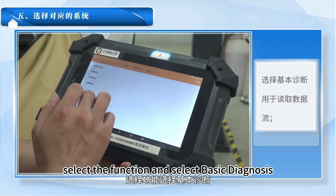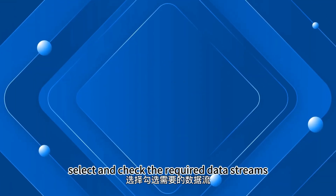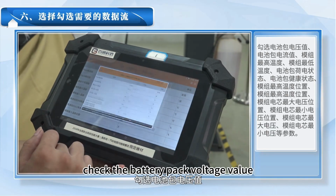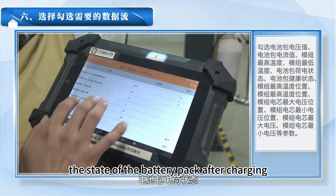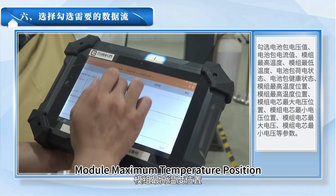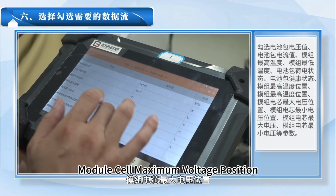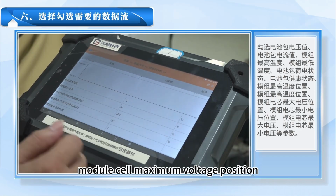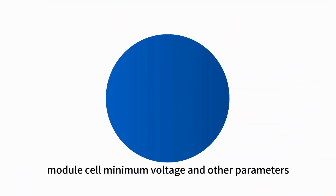Select the function and select basic diagnosis, which is used to read data streams. Select and check the required data streams. Check the battery pack voltage value, battery pack current value, module maximum temperature, the state of the battery pack after charging, battery pack health status, module maximum temperature position, module minimum temperature position, module cell maximum voltage position, module cell minimum voltage position, module cell maximum voltage, module cell minimum voltage, and other parameters.